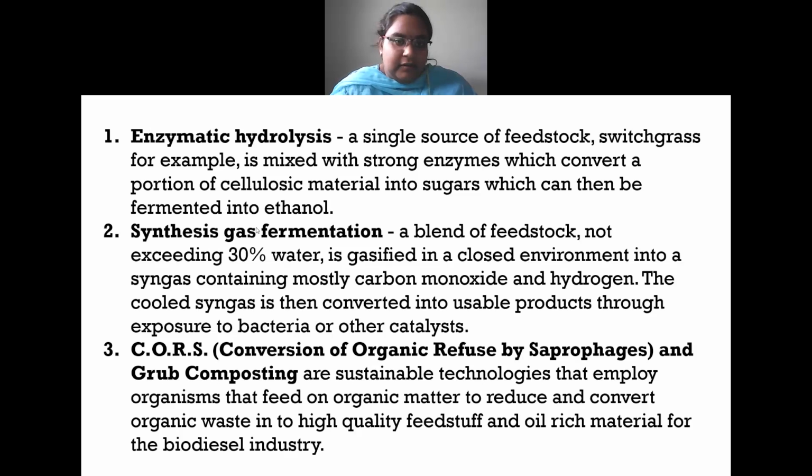Next is synthesis gas fermentation. A blend of feedstock not exceeding 30% water is gasified in a closed environment into a syngas containing mostly carbon monoxide and hydrogen. The cooled syngas is then converted into useful products through exposure to bacteria or other catalysts.